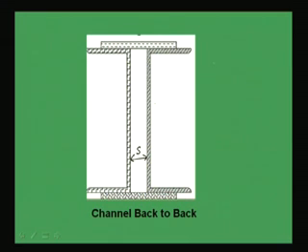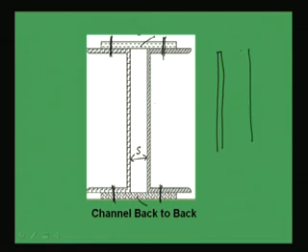Now if we use lacing or battening, say suppose this is lacing or battening, which is helping the 2 channels to act together. So if I see the view, how it will look, say this is one side, another side is this, means this is another channel. So we will be providing like this, say lacing is provided like this. This is how this will be connected.